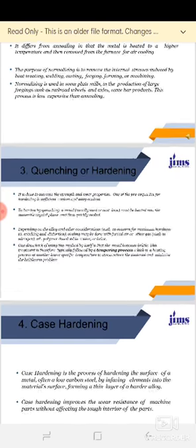This treatment is therefore typically followed by a tempering process, which is a heat process at another, lower specific temperature to stress relieve the material and minimize the brittleness problem. So after the quenching process, a metal becomes more brittle. To remove that brittleness, we do a tempering process, in which the brittleness is reduced and the material regains its original strength.